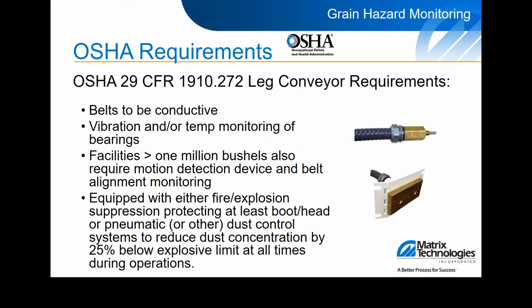Motion sensors are also used on the tail or knee pulley to monitor actual speed or provide a speed switch that monitors the conveyor, so that in the event it starts to operate at a speed lower than 20% of normal speed, the conveyor is interlocked to shut down. Rub blocks are also used to determine when conveyors get off track and have potential to rub up against obstructions, causing heat, which can get hot enough to start a fire. Mechanical alignment ruler guards can also be used to help keep conveyors on track.